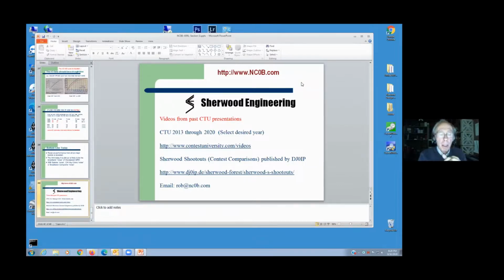That would be helpful. There's been some discussion that unfortunately some people have not been happy with, but I've been posting on a couple of the reflectors that voltage drop in your power cord is a problem. We almost never, if you don't adjust your power supply to put out like 14.5 volts or something, get 13.8 to the rig. A couple guys have said, well, they've got a RigRunner, which is kind of a nice universal thing that lets you plug in a bunch of different accessories at 13.8, but they have voltage drop. Fuses have voltage drop, and sometimes the fuse holder, that's not a particularly expensive fuse holder, has voltage drop over time. It gets a little bit of oxidation there.